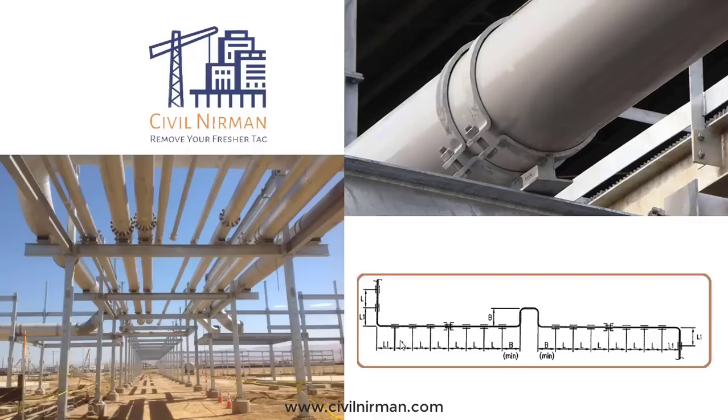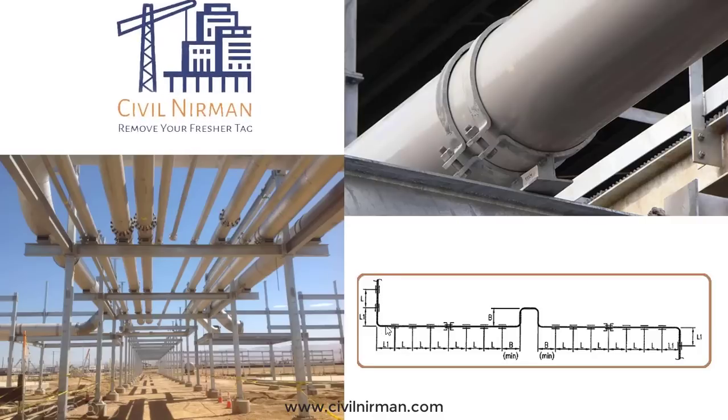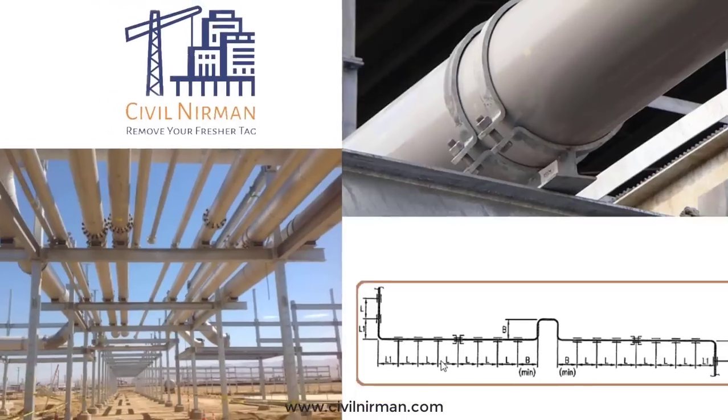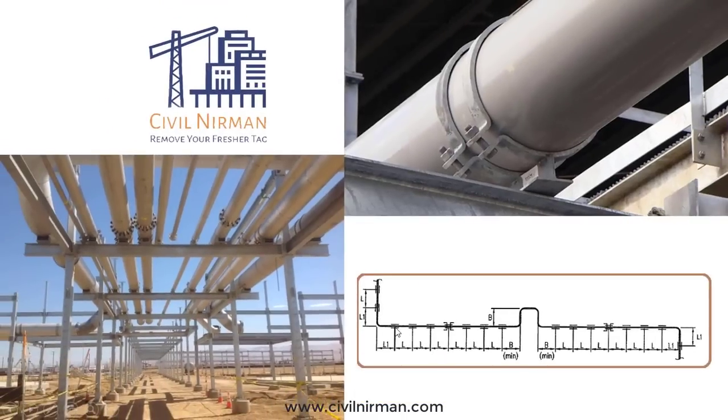Now this is the isometric view of a pipe that piping generally provides for our understanding. You can see at various locations some marking is provided and the spacing will be mentioned. The same pipeline will be running on the plot plan with this L1, L2 specified in that properly executed document. So by reading that, we can understand what kind of support will be coming at a structural location.